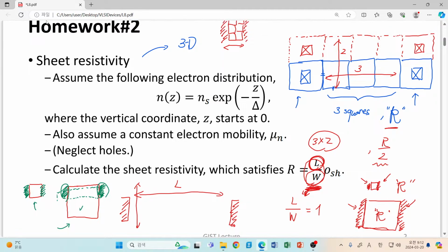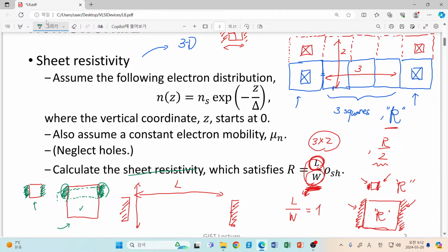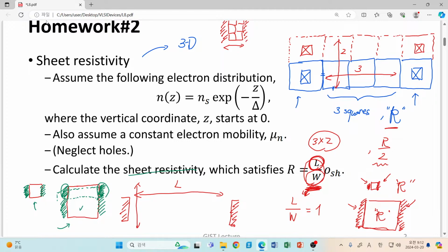So when we say sheet resistance is proportional to the number of squares, actually the number of squares along that transport direction, it just assumes that we have placed our contacts in a reasonable way, not in this weird way. I mean that this one would be quite a weird way to place our contacts. Therefore, let me just come back.